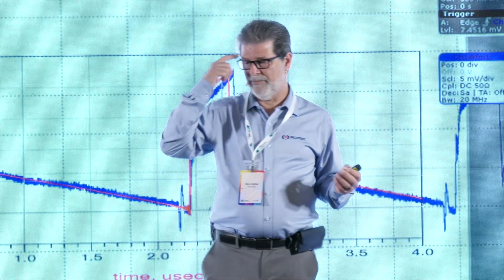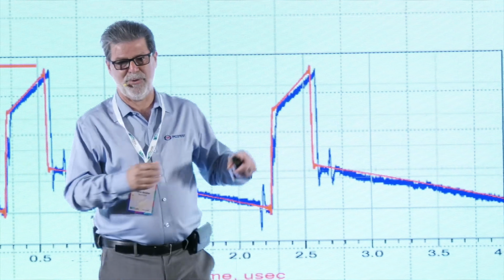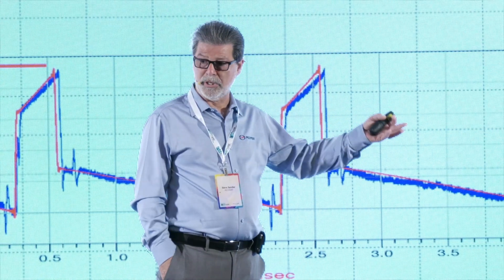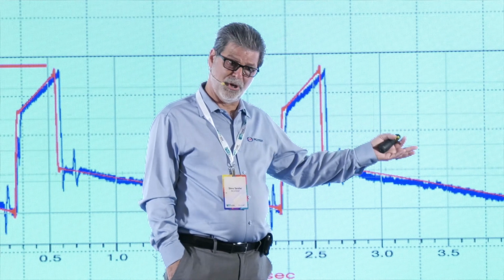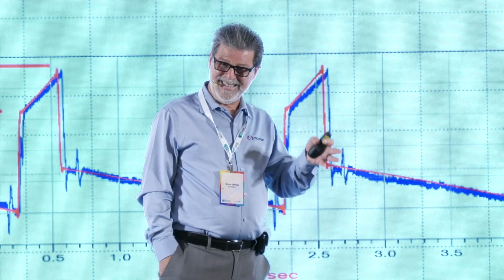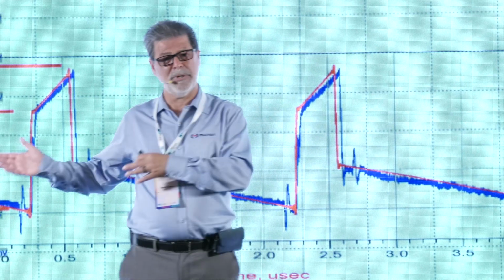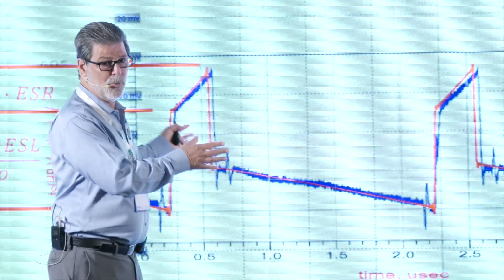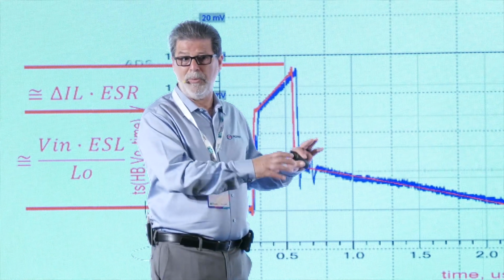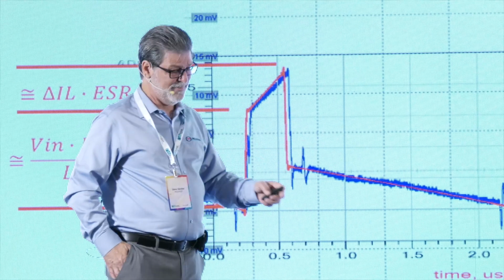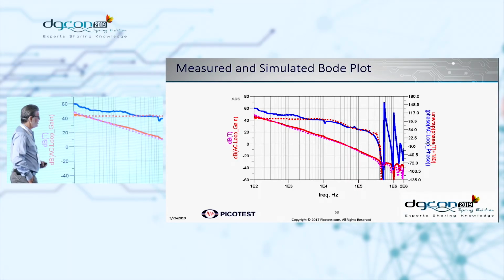So let me get this straight. You put the capacitors in to get rid of the noise. If you take out the capacitors, you'd see that noise never made it across the plane. The high-speed circuit would not have seen the noise. So the power supply guy fixed a problem that didn't exist and caused one in the process. That's frequently what happens. That's why we want all of these different knobs and why we need to know what controls what, because that's what allows us to balance all of this out. That's how we do it.